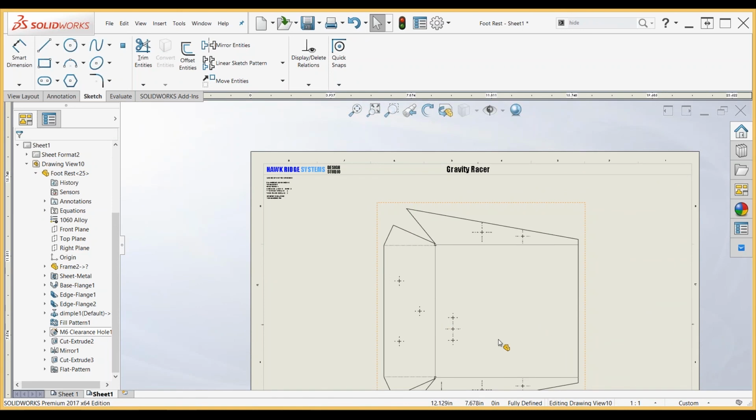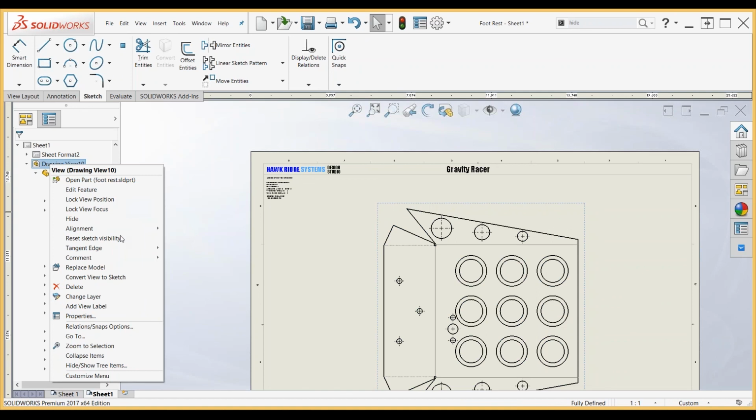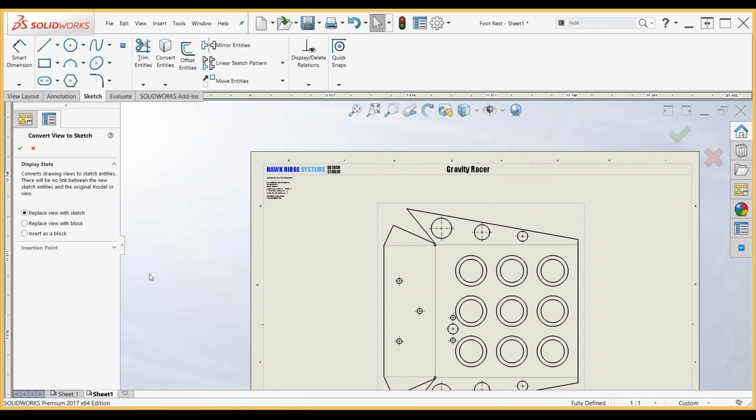So if you shrink the size of this axle, it's always going to be 2 inches from that wider diameter part. Or if you make it longer, it'll always be 2 inches. Or if you have multiple configurations of it, and you're copying your drawings and just switching the configurations, that's one way to make sure that happens in a nice, smooth, easy process.